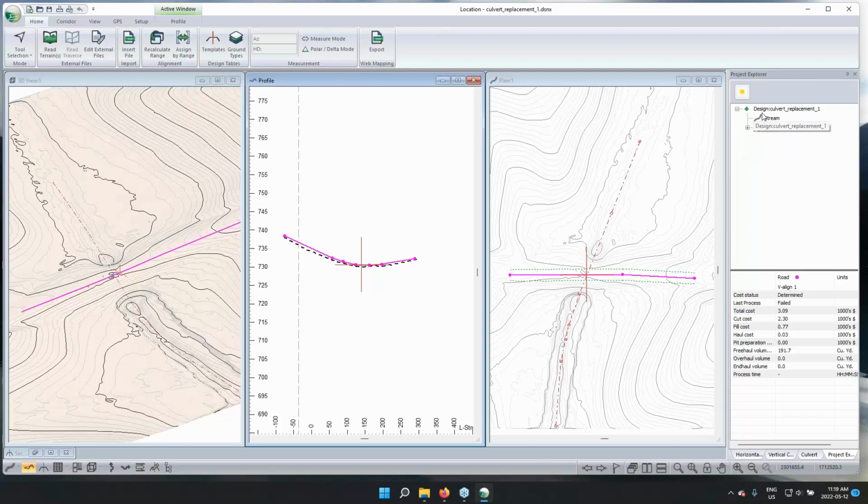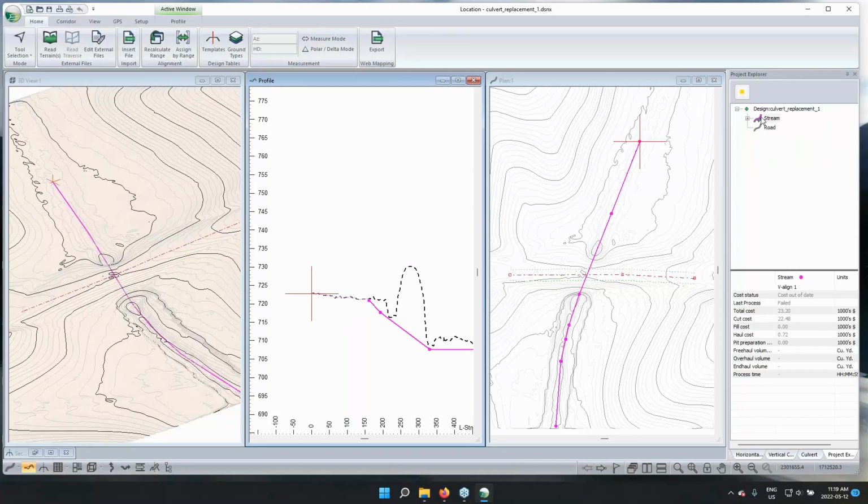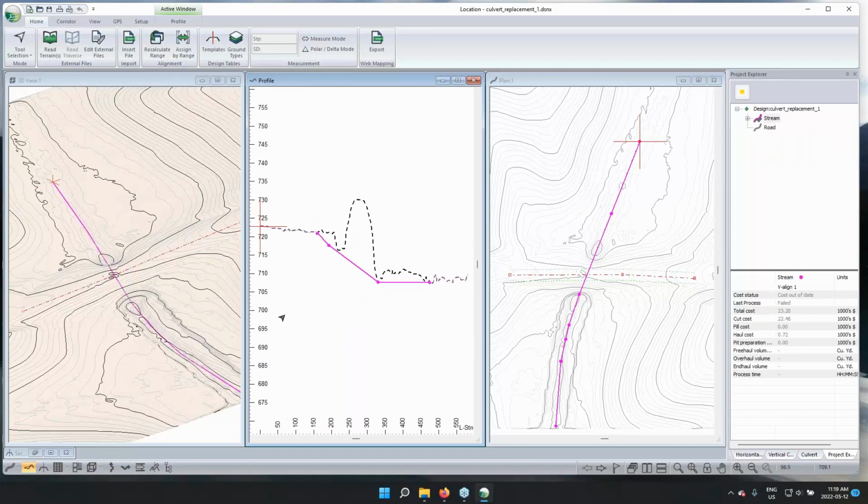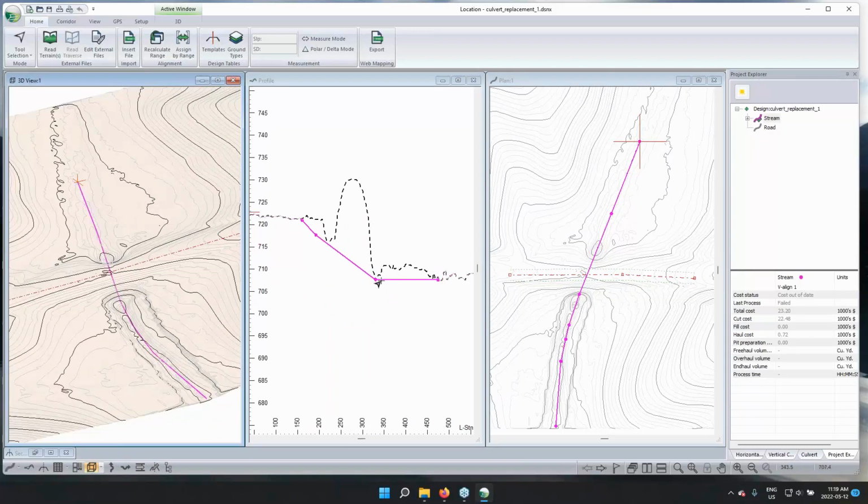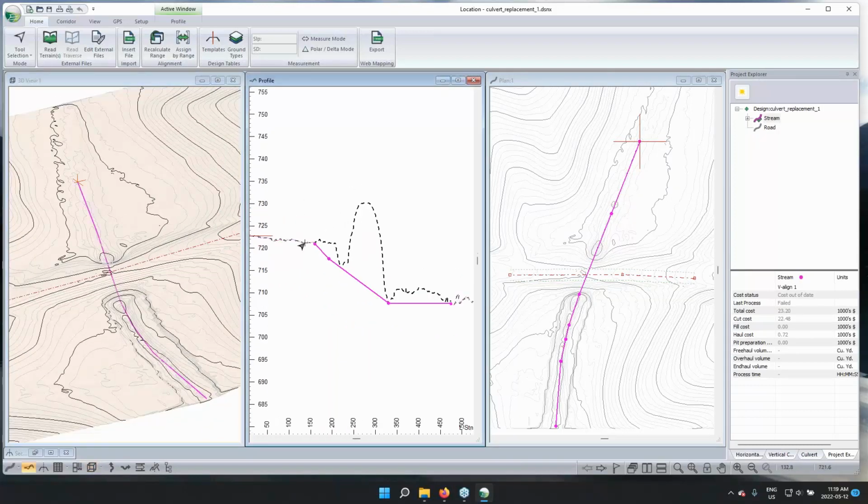So to do this, I'm going to use corridor surfaces. I'm going to go back to the stream alignment, and there's the alignment I've sketched in. This is going to be the excavated trench that I'm going to put in. So it's starting here on the alignment. It's going to go to there. I'm going to excavate that out.